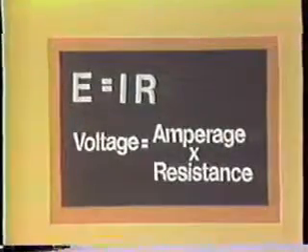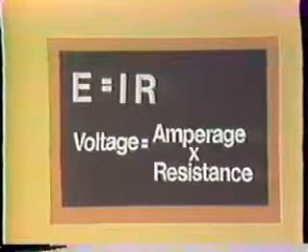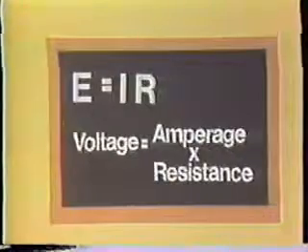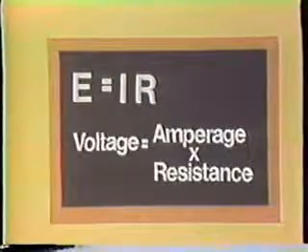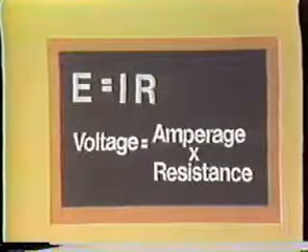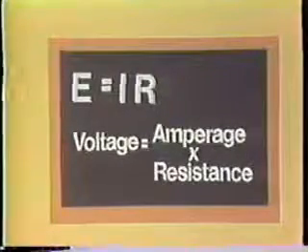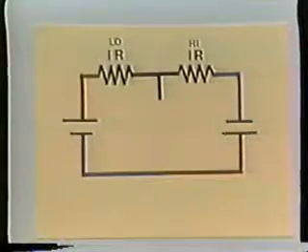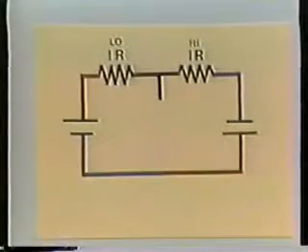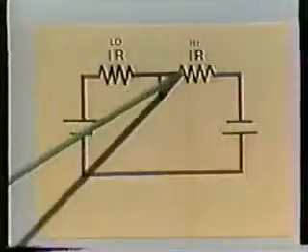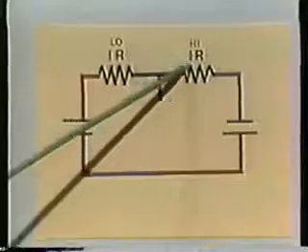According to Ohm's law, when the same current is flowing through a low ohm resistor and a high ohm resistor, a small voltage drop will occur across the low ohm resistor and a large voltage drop will occur across the high ohm resistor. The same principle can be applied to the current flowing through the low resistance forward biased junction and the high resistance reverse biased junction.